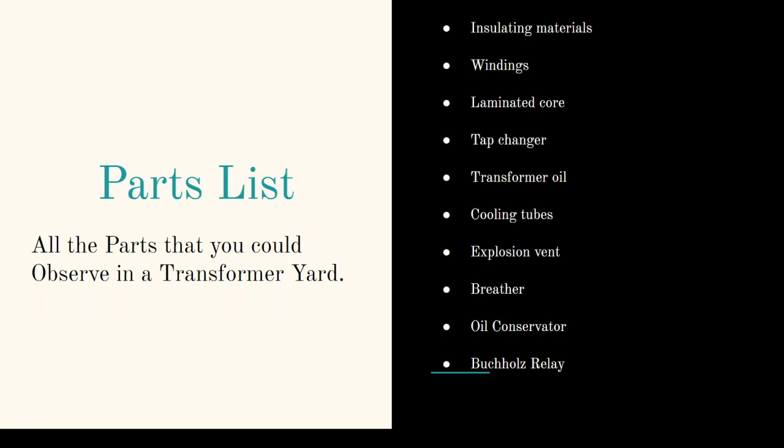Besides this, the most critical insulating material that you have in these transformers is transformer oil. Transformer oil plays the part of insulating the coils that are inside the transformer. At the same time, it also does the work of cooling the transformer. We'll talk about cooling in detail.